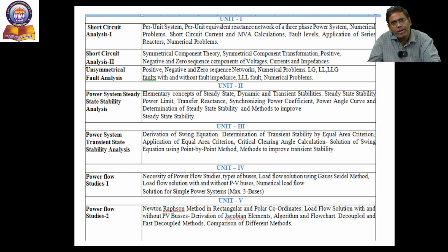The second topic is short circuit analysis 2. In this topic, we discuss symmetrical component theory, that is any phase component can be converted into symmetrical components, and symmetrical components can be transformed back into phase components. Any phase component can be represented as the sum of the positive, negative and zero sequence components, that is the positive, negative and zero sequence components of voltages, currents and impedances.